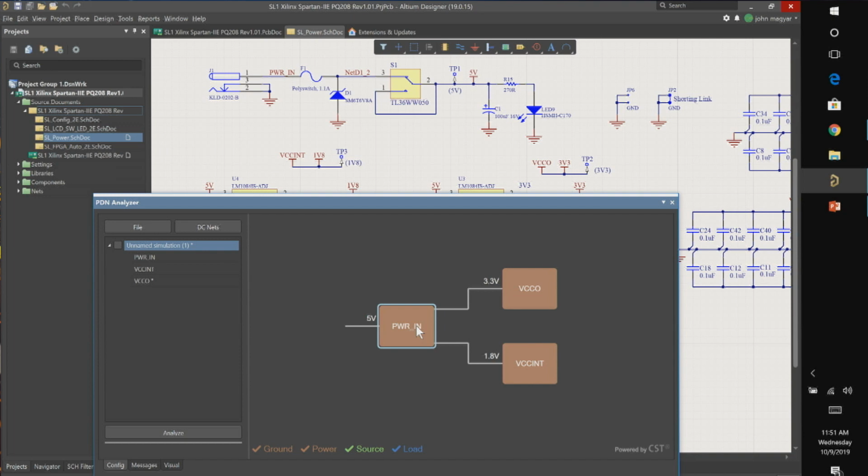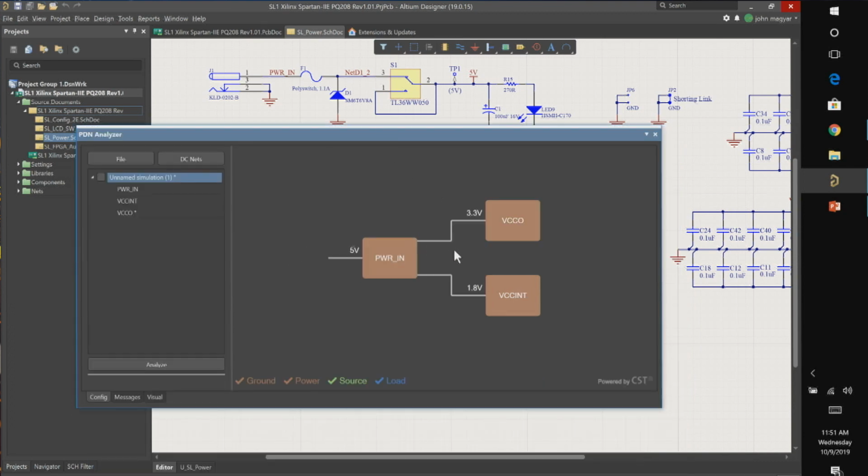So this isn't like SPICE simulation. We're not simulating versus time or relative to time. It's simply a static calculation of your supply voltage, your resistive load, and the flow of current to and from. So it's very basic, but can tell you a lot about the design. So that would be a typical setup. And for a more complex design, it's the same approach. Can generally be done fairly quickly, and once you've done a couple, it goes through pretty fast.